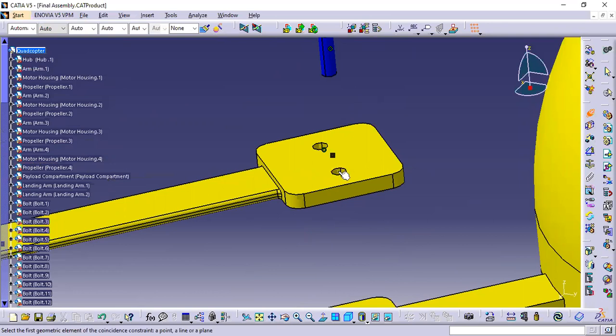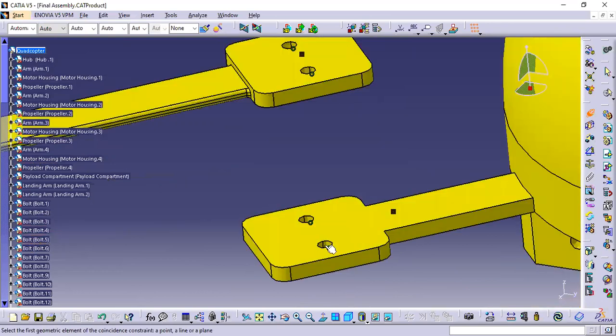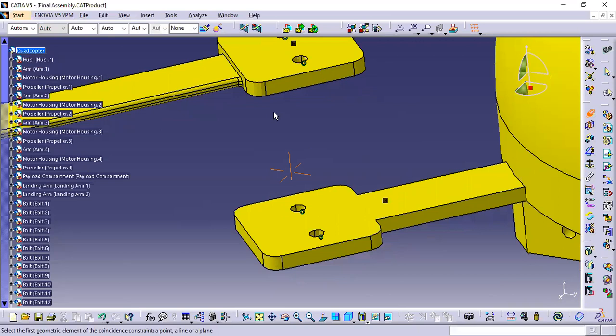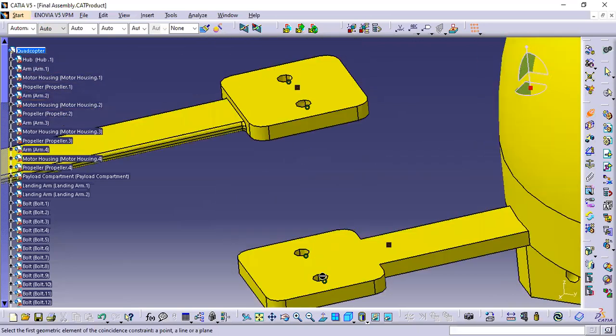Okay, yeah, this axis, and then the axis of the same hole that is existing on the other component. Of course, these holes must have the same dimension, so you can easily attach them firmly using a bolt or any attachment mechanism. So we have already constrained this one, and then the same goes for the other hole. We will constrain it with this hole until we see this constraint icon appear, which is a circle similar to the icon on the sketch platform.